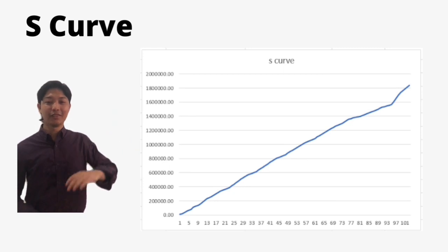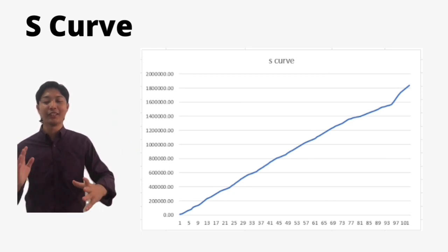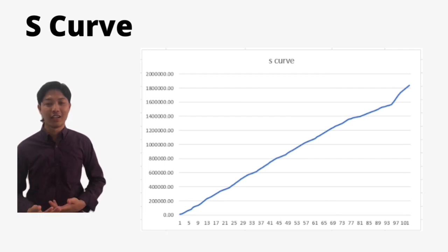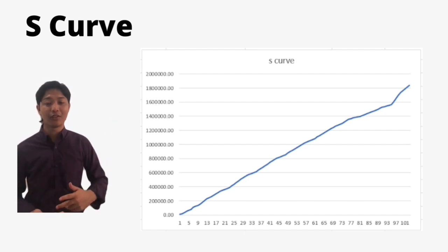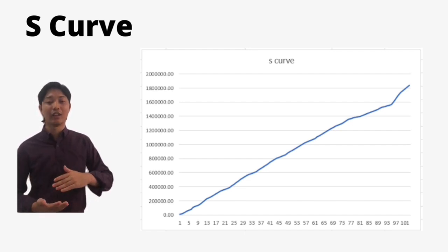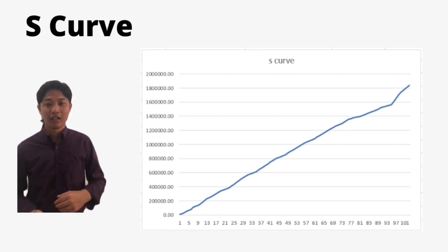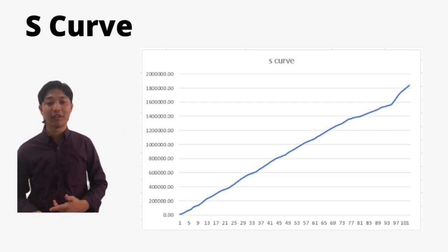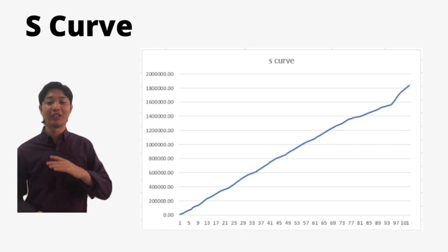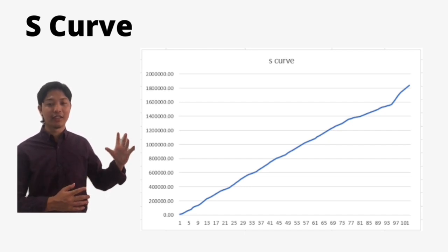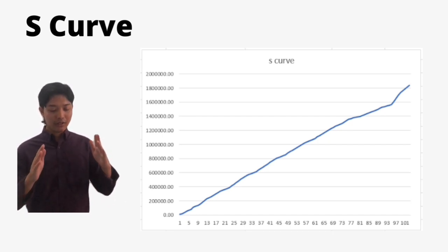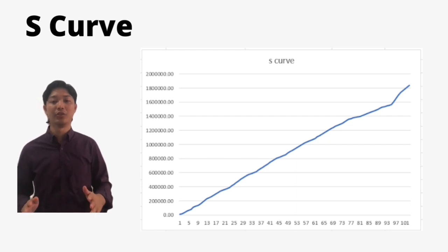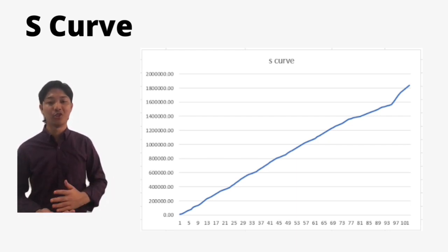This is the S-curve. The S-curve functions to track our project progress. We can also estimate our team performance based on the S-curve, and we can also see where our cost is being used. The S-curve can also display real-time cumulative data from various elements and compare it with the projected data. In the S-curve, this happens from 1 August 2022 until 11 November 2022, so around 102 days.